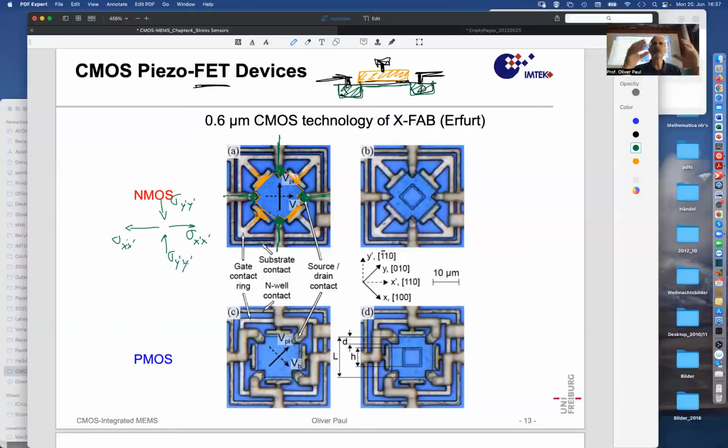Obviously not, because the 2 contacts are still symmetrical with respect to that application of stresses. Pulling along, and I like to use this geometrical picture, makes the device longer in this direction, but what was vertical in the middle still is vertical in the middle. And so there is no geometrical deformation apart this elongation. So definitely this response does not cause any pseudo Hall voltage to appear.